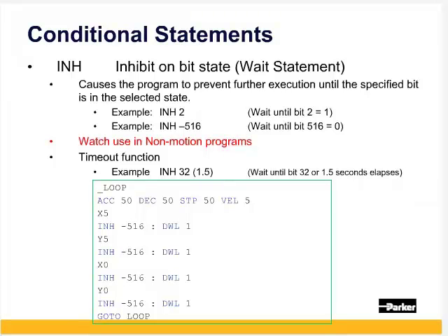The INH command inhibits program execution and waits on a flag condition to be true. INH2 waits until bit 2 turns on. This could also be coded as INH-BIT2. INH-516 waits until master 0 is not moving. INH-bit 516 is also valid.